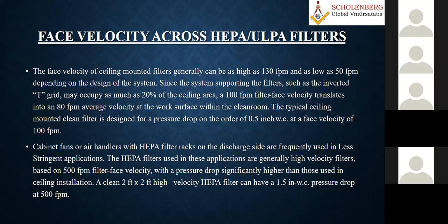In this second part, I'll be focusing on what type of velocity we normally have to consider, because it all depends upon my air handling unit. Then we will also see a little bit about the air handling units, and how we take the return air. Some places we have to take 100% fresh air. And then we will also talk about the various different kinds, like workstations, smaller ones, bigger ones, clean rooms. And finally, we also talk about the air shower and the airlock rooms, because we maintain different kinds of pressures in the clean room areas.